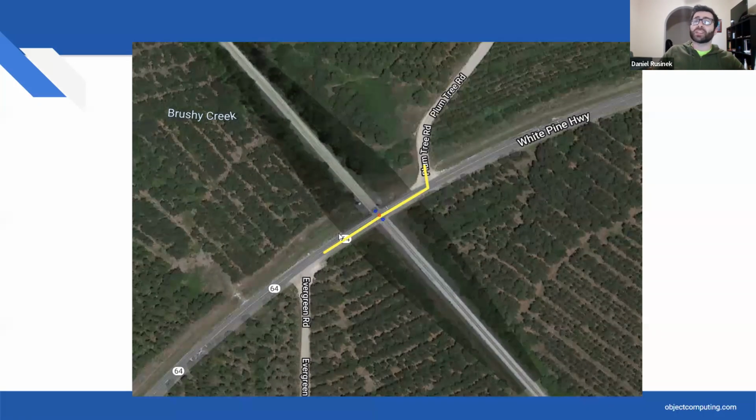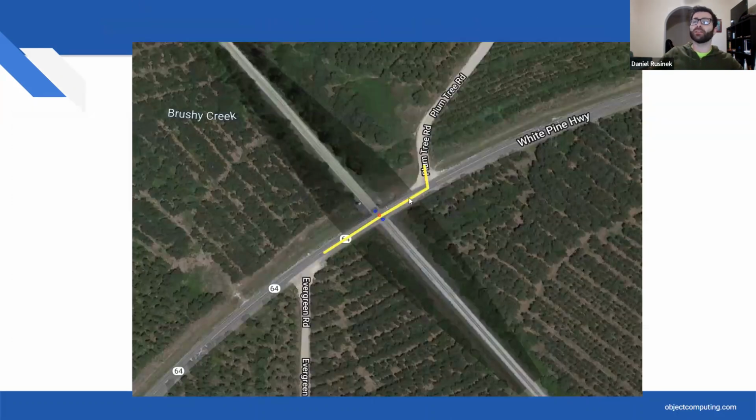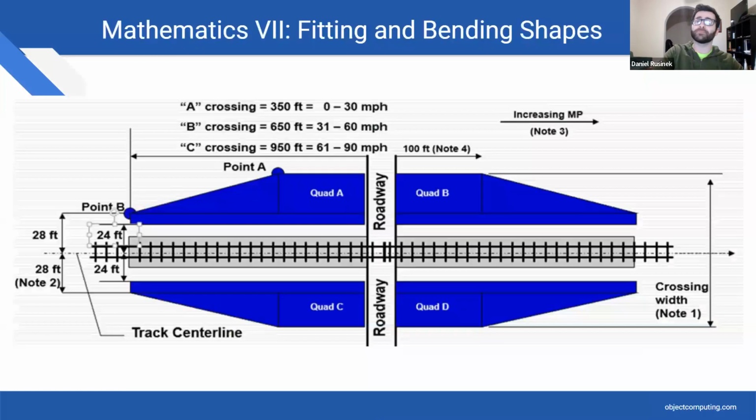So at least certain companies have decided they have areas that they define around crossings that they want cleared so that there's a good line of sight. We'll just call that the compliant shape from here on out. There are different specifications. Overall, though, the main point is that the faster the train's going, the longer the shape needs to be along the track, because the car needs more time to see the train coming, because the train will take longer to stop.